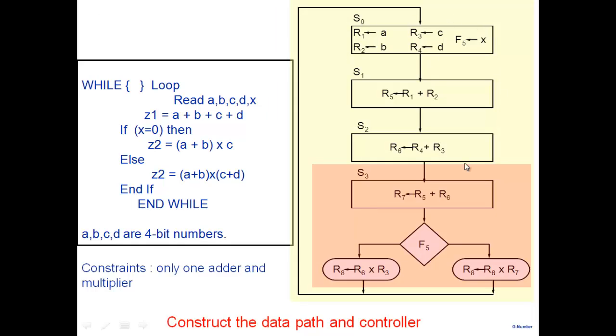What I'm saying is this is one state. Everything occurs in one state. There is a register transfer here, which is an unconditional register transfer, and this is a conditional transfer. Depending on the condition, this will occur. So I can note that I can do several register transfers in a state. A is going here, B is going here, all this is occurring.